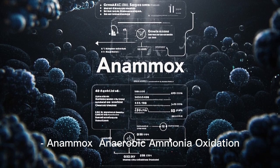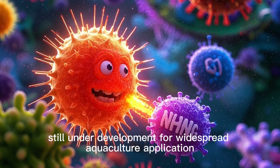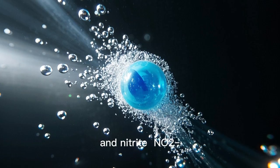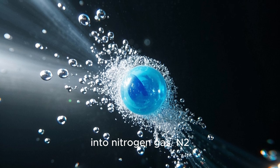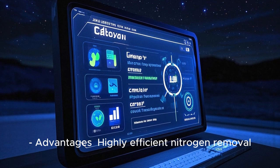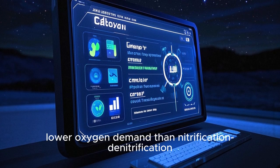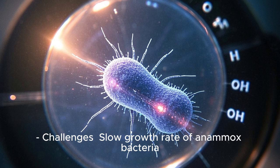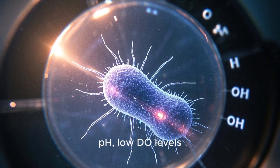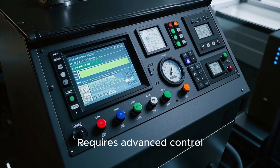And Anammox, anaerobic ammonia oxidation. Mechanism: a more recently discovered process, still under development for widespread aquaculture application, where specialized bacteria directly convert ammonia, NH4+, and nitrite, NO2, into nitrogen gas, N2, under anaerobic conditions without the need for an external carbon source. Advantages: highly efficient nitrogen removal, no external carbon source needed, lower oxygen demand than nitrification-denitrification. Challenges: slow growth rate of Anammox bacteria, very specific and difficult to maintain operating conditions, temperature, pH, low DO levels, susceptible to inhibition by various compounds, requires advanced control.